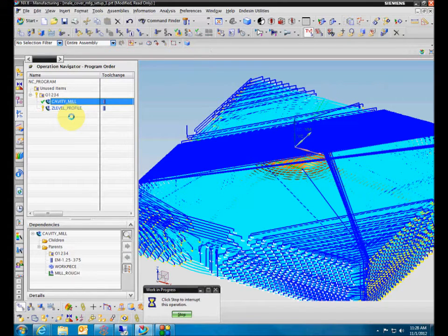And the benefit of this is, it allows you to put the tool as far into the holder as you can, which makes the tool setup more rigid, which extends the life of the tool again, improves surface finish, and also improves the accuracy of the finished part.